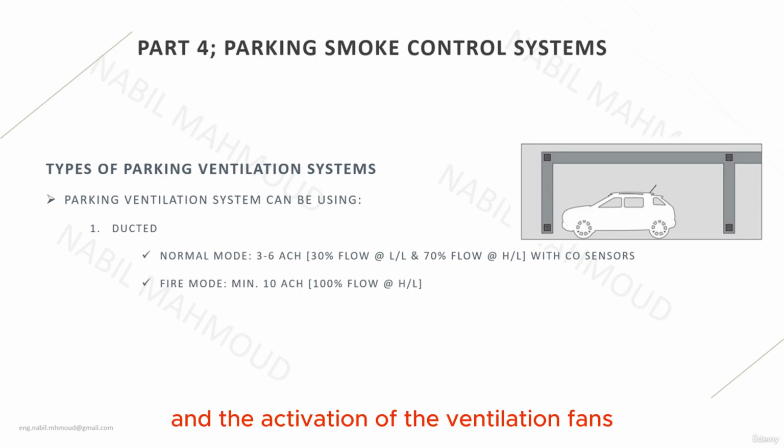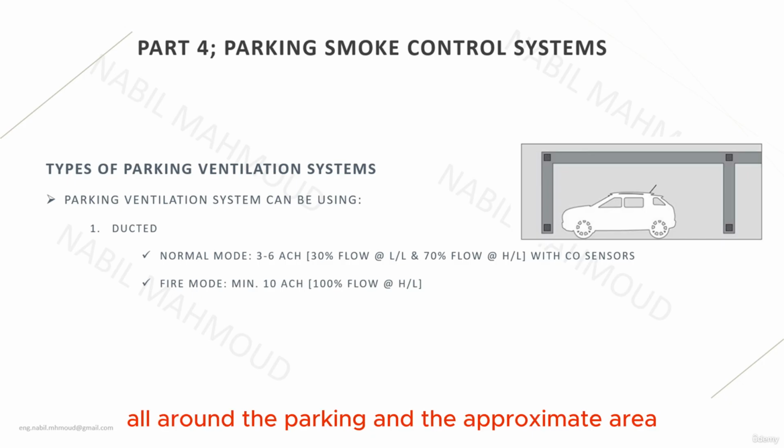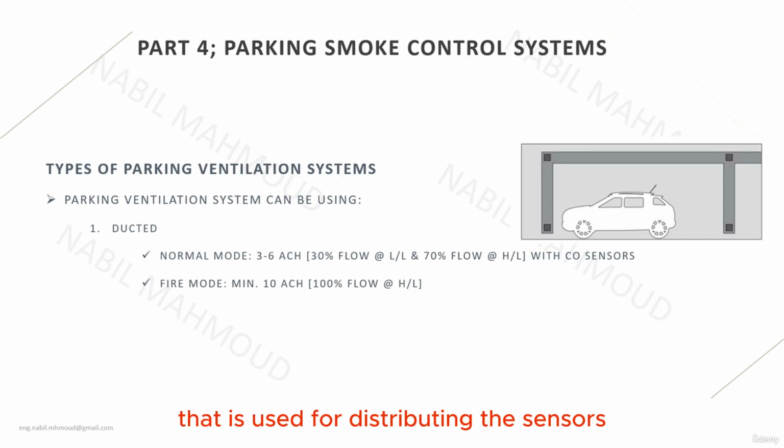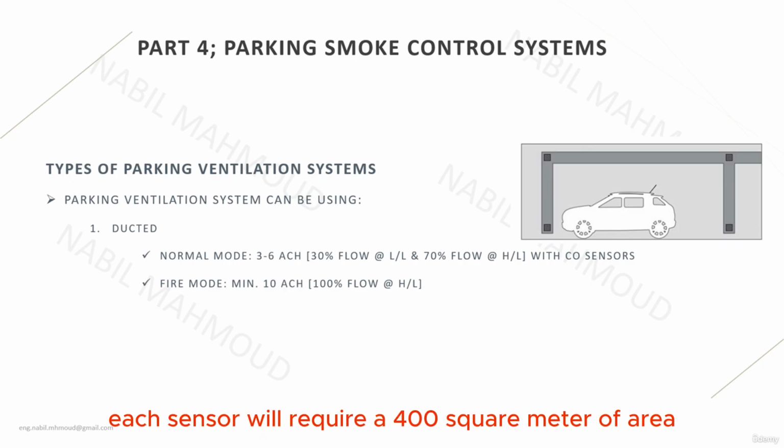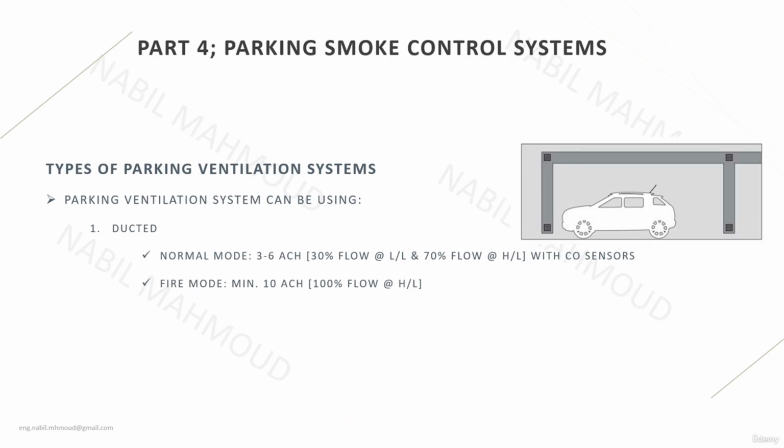And the activation of the ventilation fans will be triggered by CO sensors, or carbon monoxide sensors. Why carbon monoxide? Because carbon monoxide is a poisonous gas, and if it accumulates inside the parking, it can cause serious health damage. That's why we distribute CO sensors all around the parking, and the approximate area used for distributing the sensors is that each sensor will cover approximately 400 square meters of area.